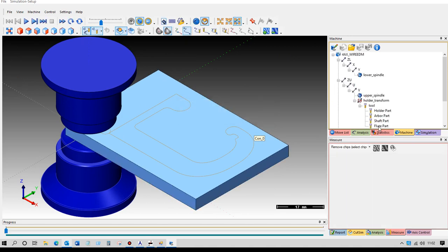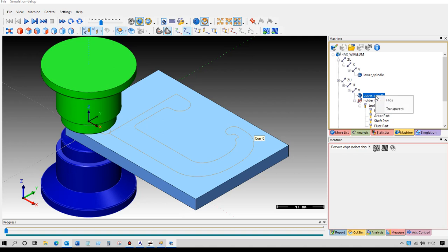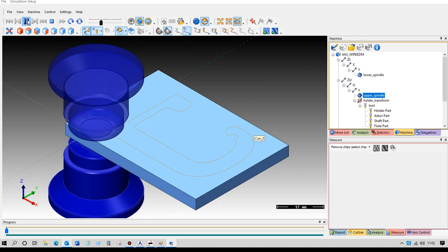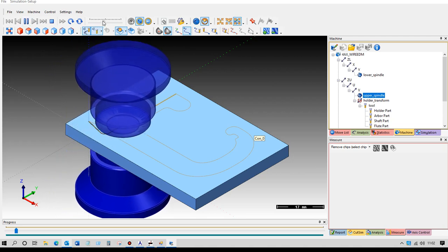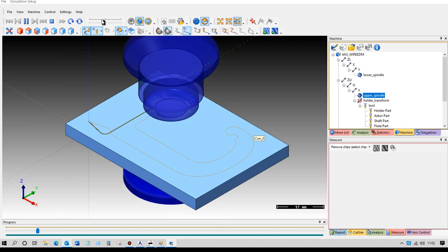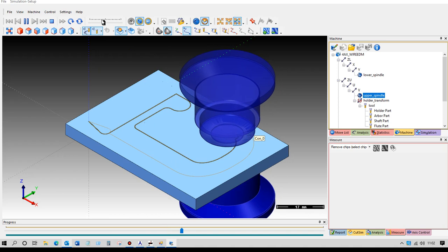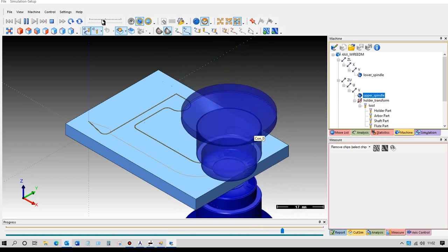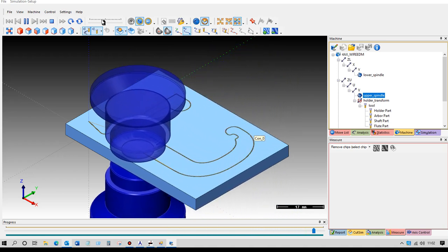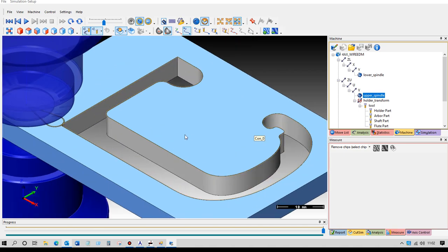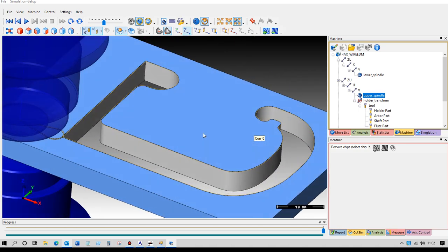This is the top and bottom wire guides, but if we want to, we can come across here and we can make those transparent, and we can just replay the toolpath. We're not going to see much difference here to what we did in the standard wireframe, but if we were using tapered cutting or 4-axis work, obviously we'd see a better representation of how it's actually going to cut. And if we want to get rid of the center shape there, we just click on it so we can see that there. Okay, so that's how we produce the part for that file.